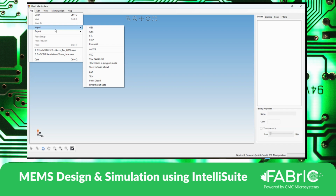In the case of MEMS, it will typically be in terms of micrometers. So FDTD is applicable. But what I would recommend is if you have a tool like Lumerical, which I had tried much longer, we can play with the STL file. The STL file from Lumerical can be opened in IntelliSuite, and then the deformed structure from IntelliSuite can be opened in Lumerical.